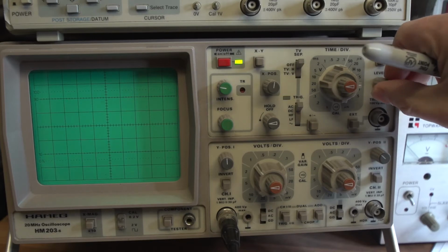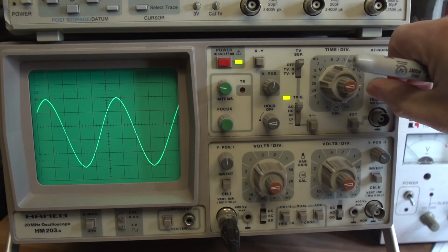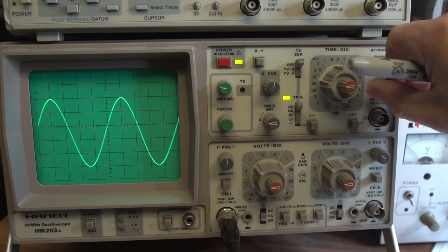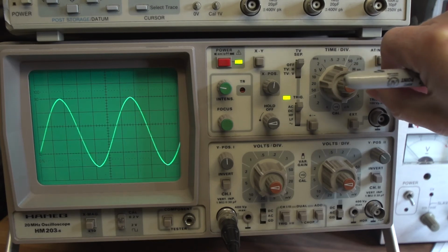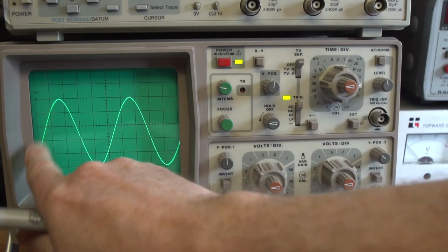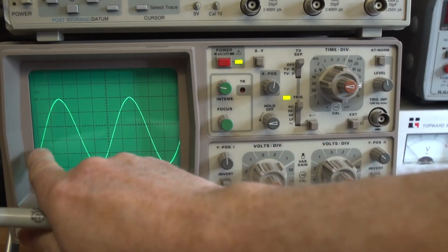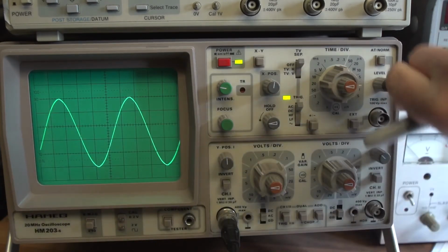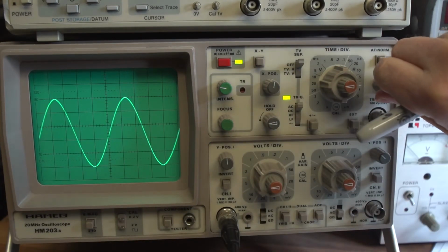And you can see, actually the beam's gone completely. I'm triggering at different positions within the waveform. That's why it looks like it's moving left to right. We're actually picking a different point to trigger from. I'm turning it up, I'm turning it down. So it looks like it's moving the actual waveform.